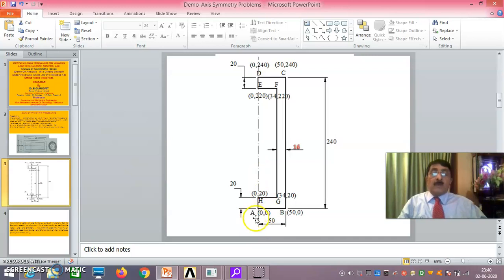Now for modeling, I'll consider points A, B, C, D, E, F, G, H, and back to A. I'll create these points and convert them into an area. Otherwise, you can make this area, and this area, and this area, and unite all the areas using Boolean add areas. You can do it that way also. Now I am showing you a different option, where I create key points and make the areas directly.